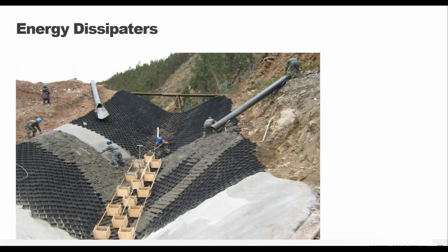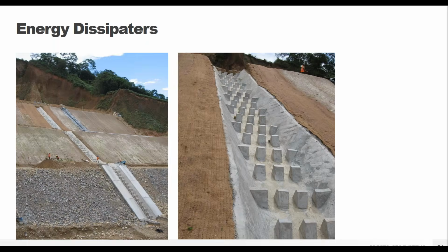Okay, and then the other special condition is incredibly high flow situations where you need to slow that water down. When you need it slowed or even stopped, because potentially you're going into a natural drainage area that can't handle high velocities, one of the best ways to do that is with energy dissipators. Energy dissipators can be added to any concrete filled GEOWEB channel, and they can be as low tech as simply placing boulders over the panels to something a little more uniform, with a nice patterned layout of dissipators, but they can definitely be included as necessary.